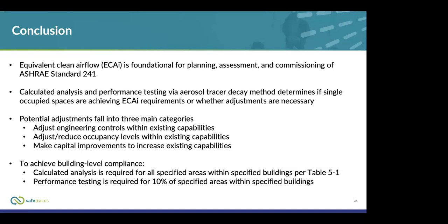Secondly, the calculated analysis and the performance testing via aerosol tracer decay method determines if single occupied spaces are achieving the equivalent clean airflow requirements or whether adjustments are necessary. So the aperture of the performance testing is a single occupied space, with guidelines in the standard on what's the sufficient scope of testing for a building, and then the calculated analysis is addressing all the relevant spaces laid out in table 5-1 that you need to be concerned with in the building.